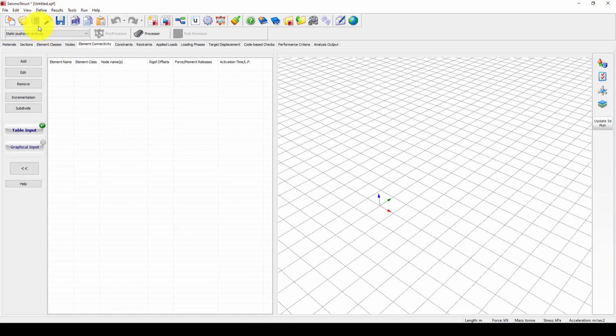Now it directs us to define some accelerogram that you want to apply in this model. So I'm taking the Kobe earthquake. When you come to here, you can define the description, and you can select the first point from here, and the method is time and acceleration. It asks me for the acceleration column, which is column 2, and the curve multiplier, which is G, which should be 9.8 here, and it's okay. Now you can see the graph is here. You also have the right to scale it, make it 1.2, 1.5 to see the response of the structure. So now it's okay, we have created it.